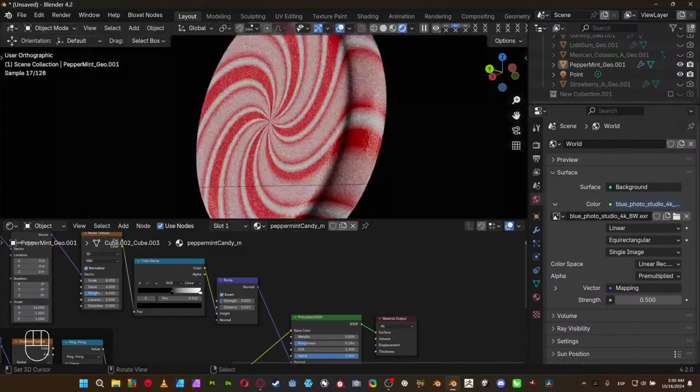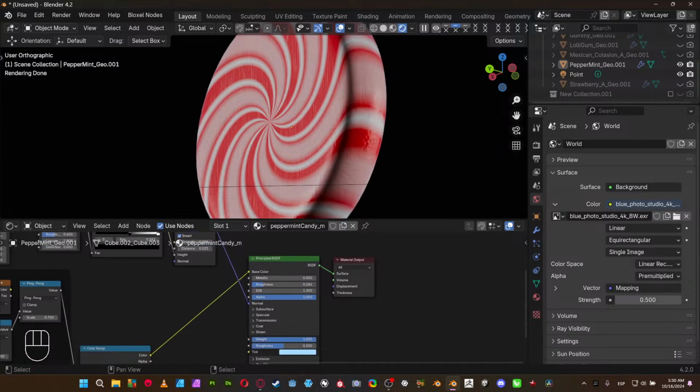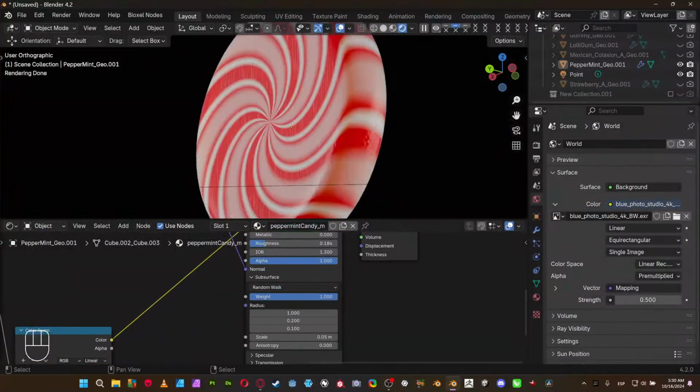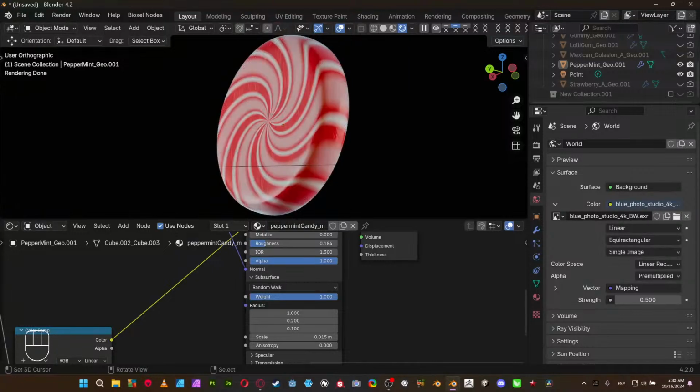It looks pretty good actually. Really nice. You can add subsurface scattering, but it depends on you guys. If you put a lamp behind these in real life, they have translucency. Let's just add it, just in case. 0.015. And there you go. That's it. No more.